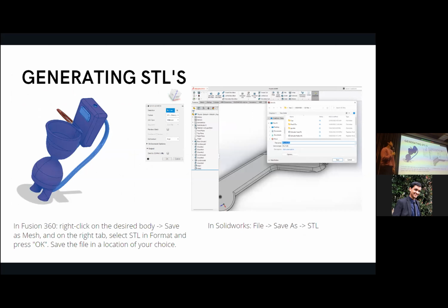Enjoy. So, when we want to convert a file that we make, like a 3D model that we make, into something that can be understood by a slicer: usually, CAD programs store files in proprietary formats, such as SolidWorks, where you have the SLDPRT file. We can't really use that for a slicer. We have to convert it to STL.